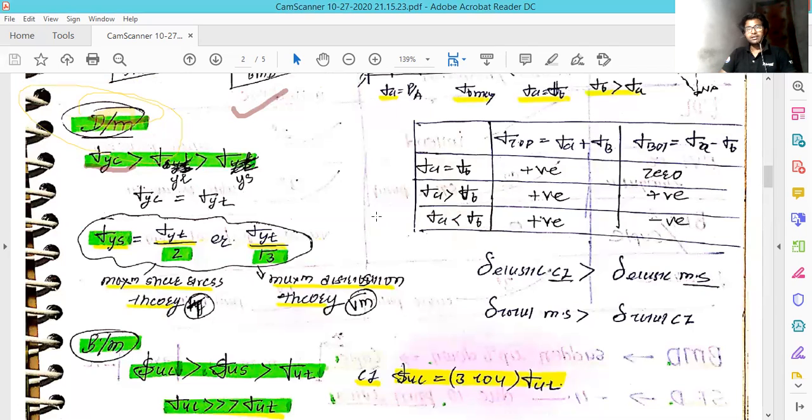As we know, if you apply tensile stress on ductile materials, what will happen? It will get elongated, and after that, it will reach the ultimate point and then start breaking. In compression, the same stress-strain diagram applies, but in the negative direction. But if you apply shear stress, which is trying to twist the material, it is not able to sustain that much force. So for the same material under these three kinds of forces, it will sustain more compressive stress compared to tensile stress, and it is least efficient for shear stress.